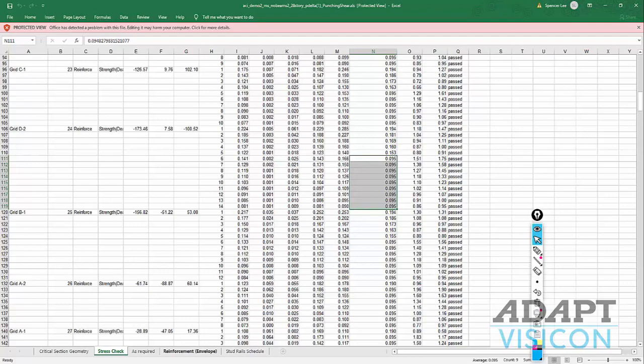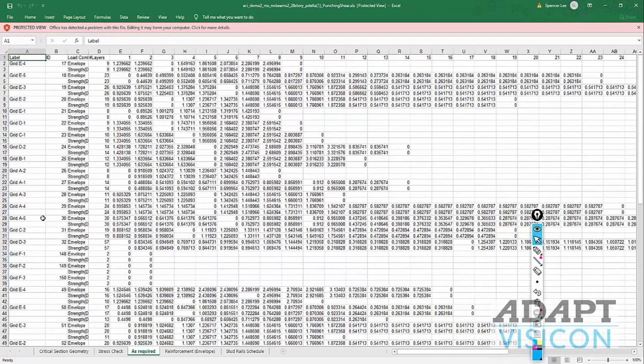The third indication would be the area of steel required. Coming down here to column D2 for strength, at section 5, the amount of reinforcement needed based on a rectilinear section is 0. At that point, we recheck it based on the octagonally shaped section, and there's additional reinforcement needed out to layer 14 until we get back to 0, meaning we meet that allowable stress condition of 2 square root of f prime c.